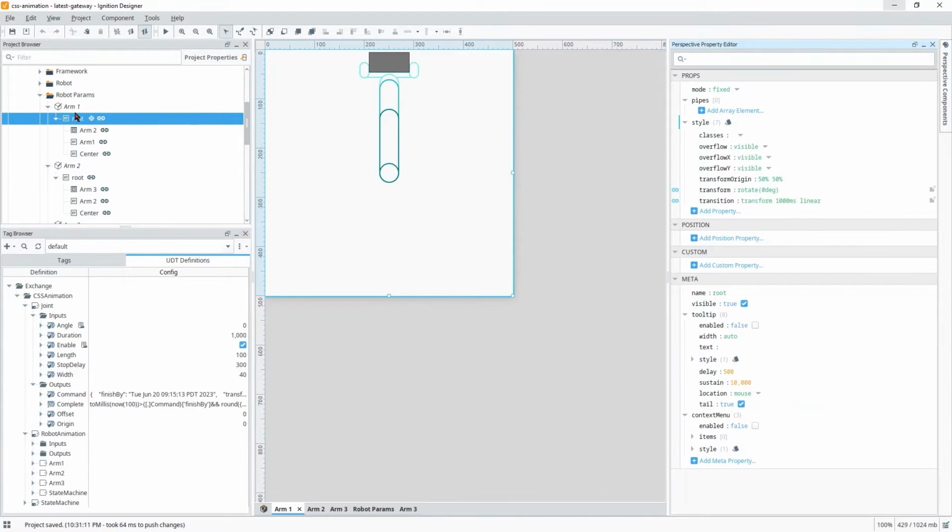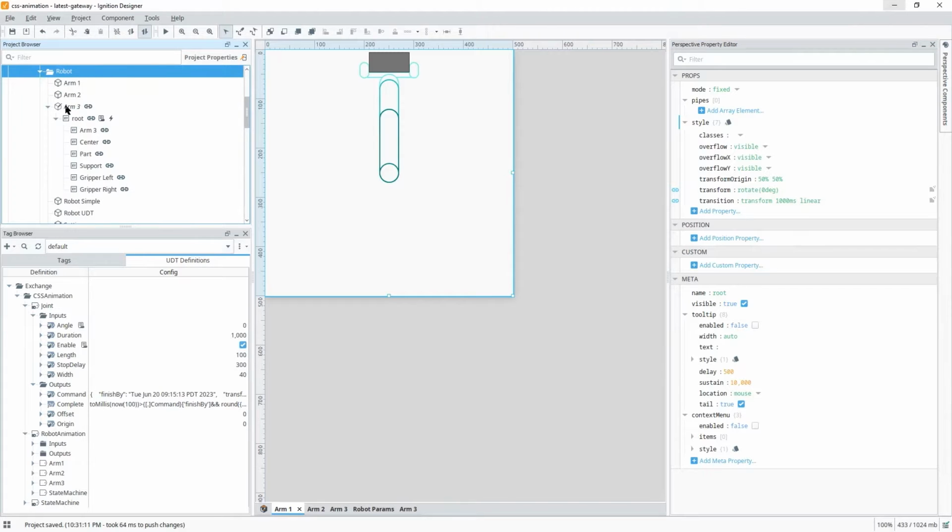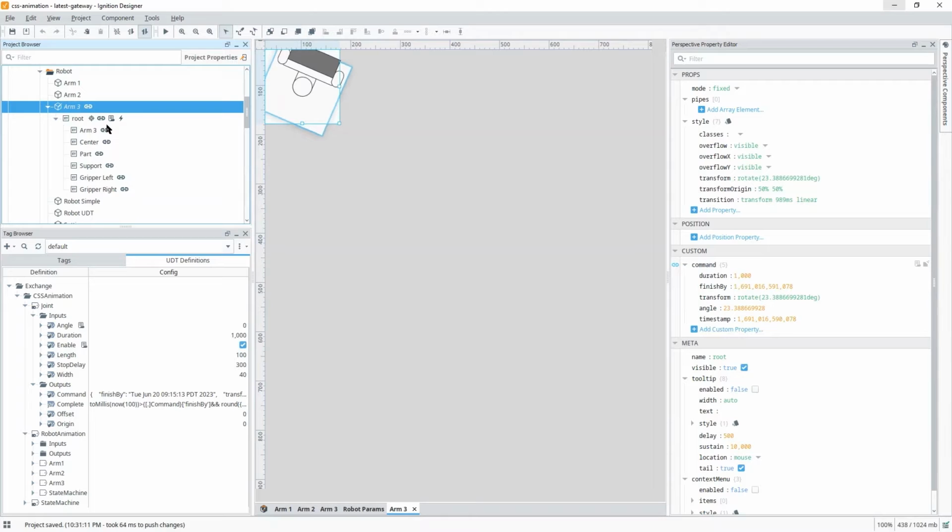take a look at the regular robot folder in here. We have robot 3 open, so let's go in that. To convert it to a closed loop system, what we have to do is calculate the time and place where we want things to be by. You can look here and you'll see that this is not saying exactly 1000 milliseconds or 2000 milliseconds.